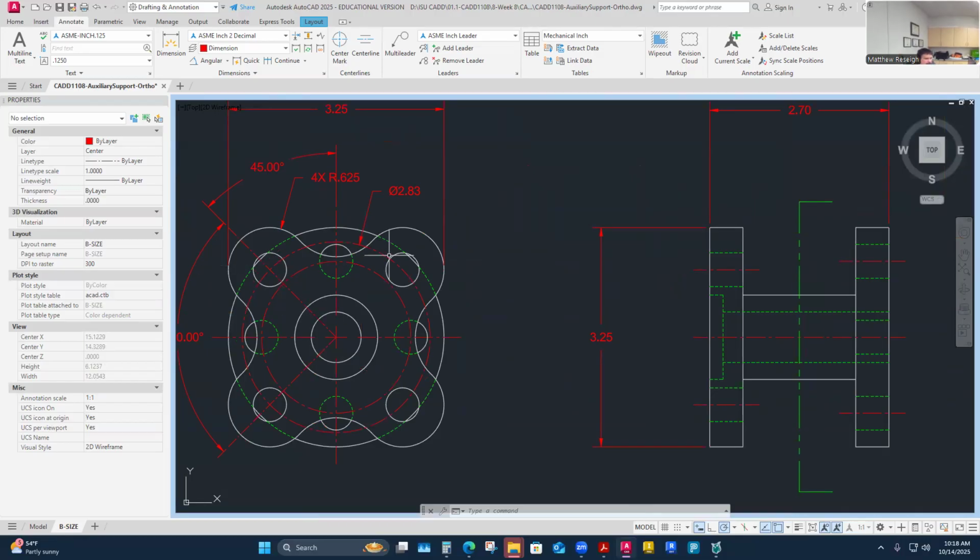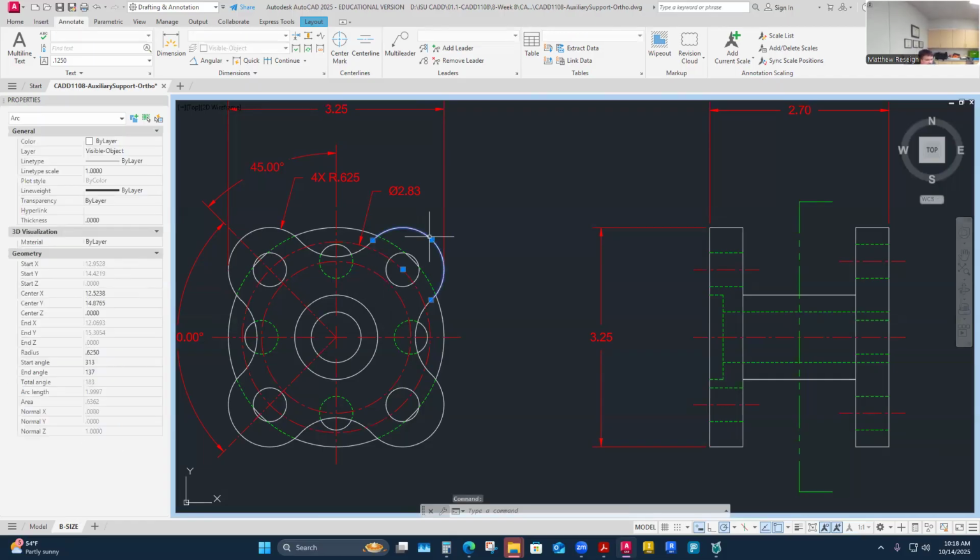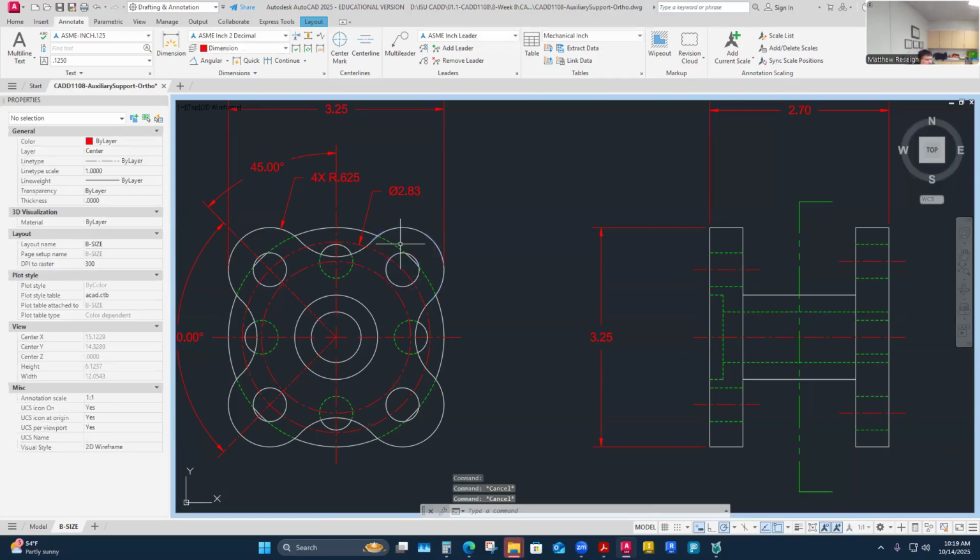So I'm going to ignore what I did on the left side of this. I'm going to focus on rectangular coordinates on the right side. What that would look like is, if I'm just thinking of this feature, I'm thinking that it is concentric to this feature. So these are going to also do double duty for both of these features. I would still need the size, so I'm going to pretend I don't even have that size. I would definitely need the radius called out. That's a critical dimension. You've got to have the radius.